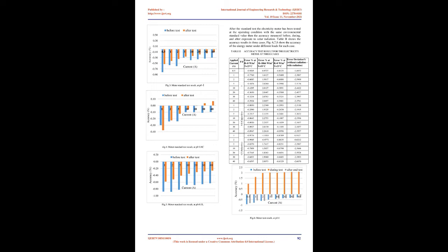3. Solar test procedure. According to the IEC standard, the protection against solar radiation test is performed on the electricity meter for 3 consecutive days, where the energy meter is in non-operating condition, placed inside the climatic chamber, and exposed to solar radiation with temperature 55 degrees Celsius for 8 hours, and 16 hours in darkness with temperature 23 degrees Celsius. Then the meter's accuracy is recorded before and after the test. The energy meter was tested by the standard method.